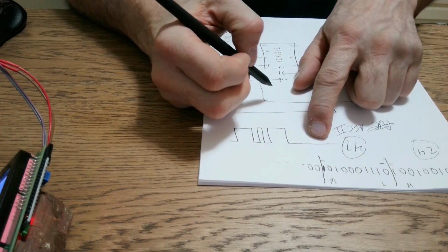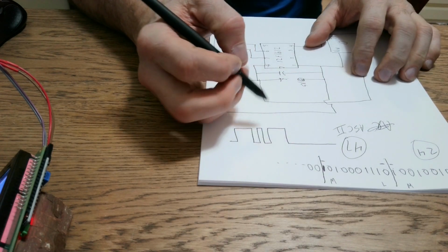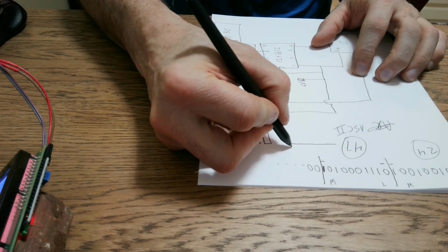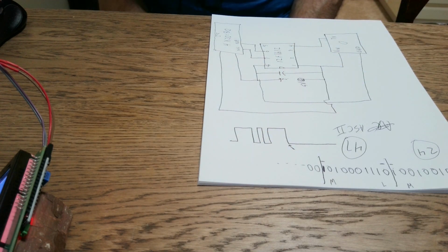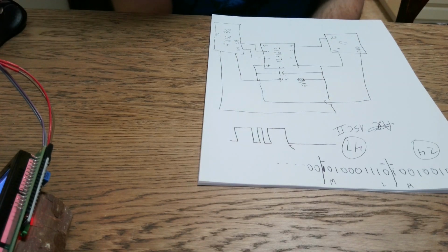So here's your waveform that came out from that TX line. It's obviously high for a long time, and I'm waiting for this moment right here in time where it finally goes low. It looks like high to you, but it's low in this picture here. And that's the point where the data starts.